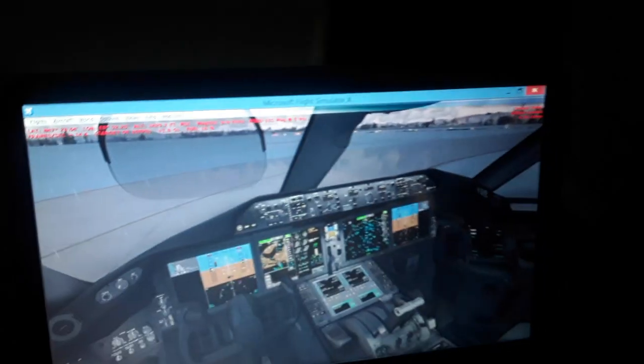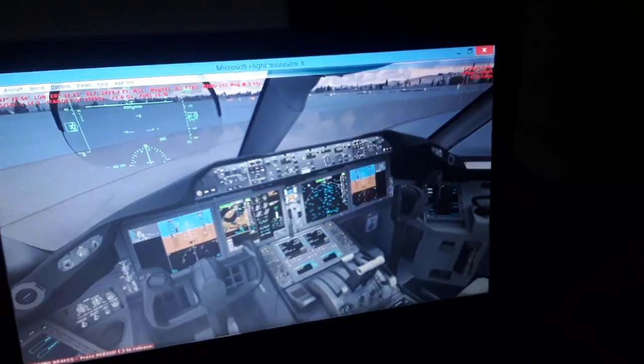So you can see, the flight management computer will calculate also the aerodynamic core position, 33% of the Mach. It will calculate a few more things, the center of gravity and the horizontal trim stabilizer. We're gonna use the flaps for takeoff 15 degrees, and we're gonna select the runway we're gonna use for takeoff in the Zurich International Airport, the LSZH.